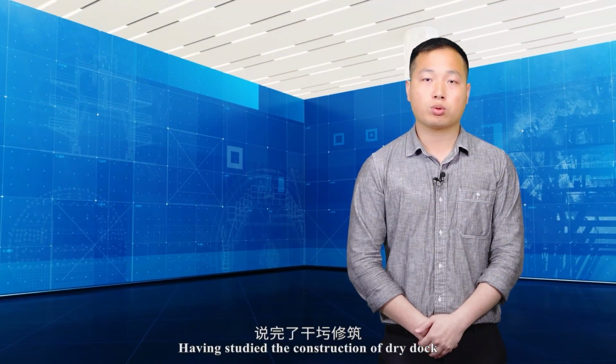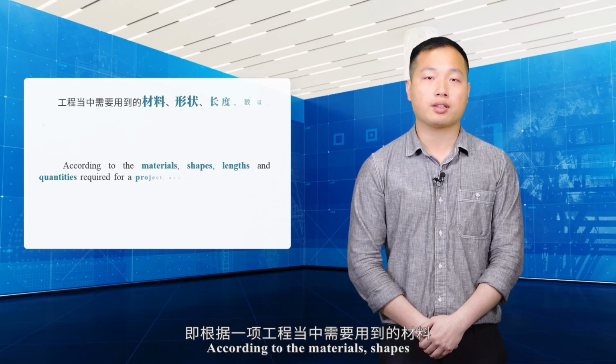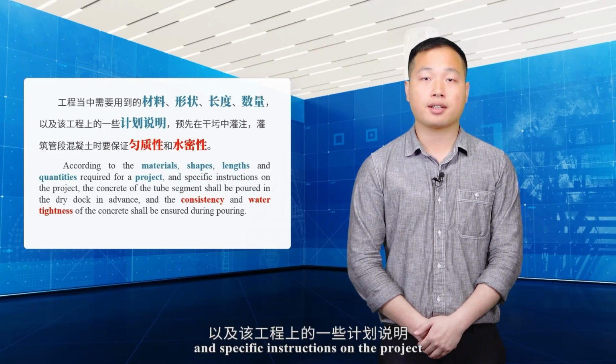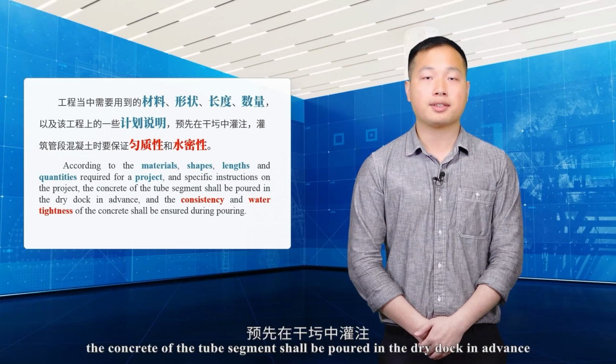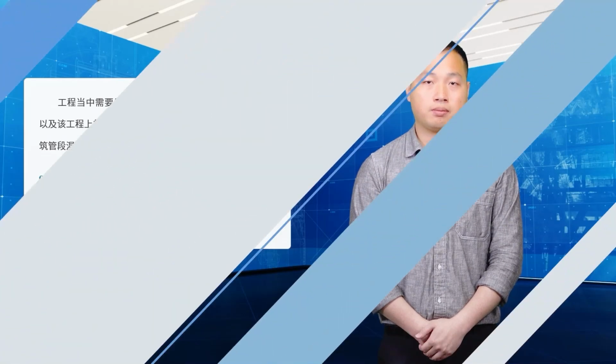Having studied the construction of dry dock, let's move to the prefabrication of tube segments. According to the materials, shapes, lengths and quantities required for a project, and specific instructions on the project, the concrete of the tube segment shall be poured in the dry dock in advance, and the consistency and watertightness of the concrete shall be ensured during pouring.